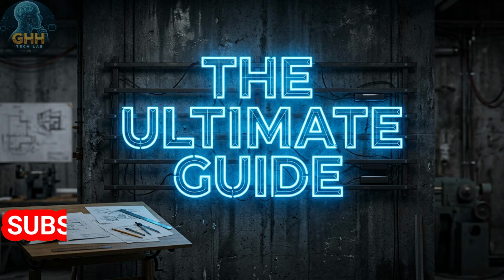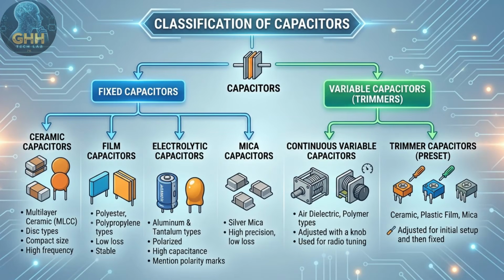Today, we are breaking down every major type of capacitor on the market. We'll look at their internal chemistry, their ideal use cases, and the exact physics behind why you need different dielectrics for different jobs. At the highest level, capacitors split into two categories: fixed, which have a set capacitance value, and variable, or trimmers, used for fine-tuning radio frequencies.